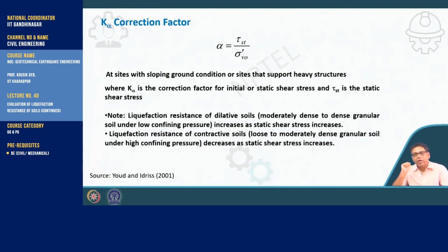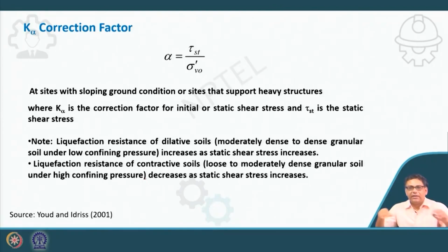Clear? Suppose you have a soil with no structure, a flat land. As I have shown, there is no shear stress on this particular plane before applying the shaking, but when we apply the shaking, the shear stress will develop.